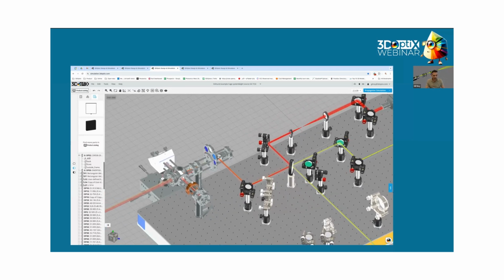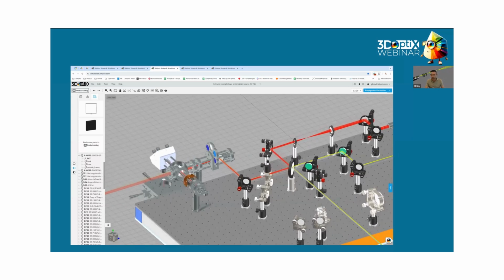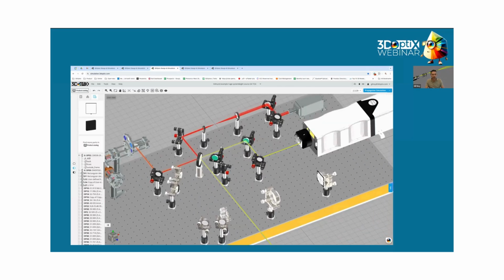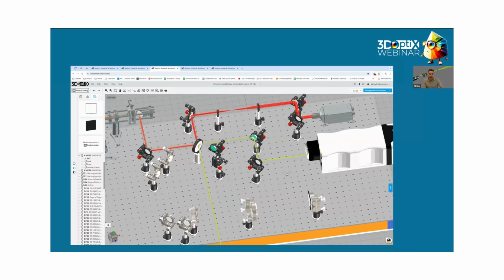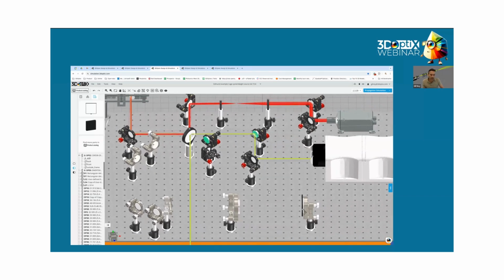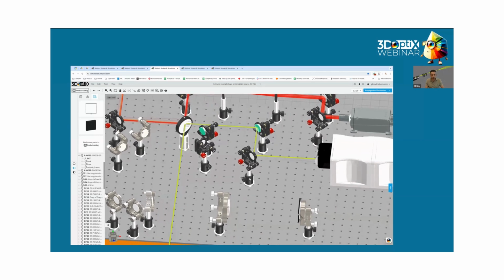And you can see here from the Michelson going here to that focusing lens. And this is a pump that's going in as well. So what we are showing here is adding a delay line via a very simple way of doing it. So let's go and change the location of this element, and you've seen it earlier. So I'd move this, but since I reference it, so all these three would move.